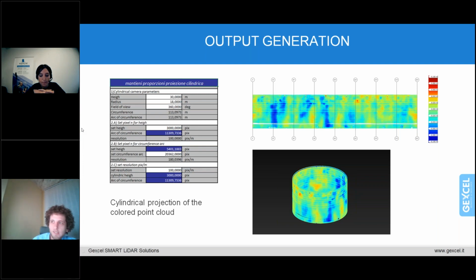The data we have in AutoCAD, we also have to find a way to migrate into Reconstructor as a common platform. So we have the point cloud exported from Faro Scene, and we have the cylindrical as-planned model from CAD, all put within Reconstructor. The inspection tool from Reconstructor works like that. When you have a mesh and a point cloud, it can analyze and calculate the distance for each point. This dataset consisted of like 160 million points from the laser scanner.